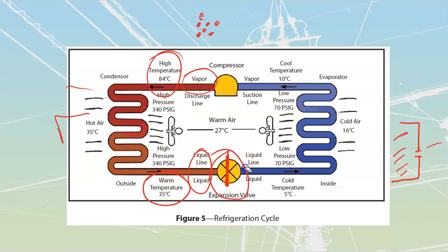And then we pass that liquid through the orifice over here. I want you to imagine that you got your mouth full of water, and then you do the thing as a kid, you fill your mouth full of water and then you kind of spew it out and it comes out sort of as a mist at times, right? What's happening is, by dropping the pressure, it's high pressure inside of your mouth, as you send it out, some of it is evaporating at that point.